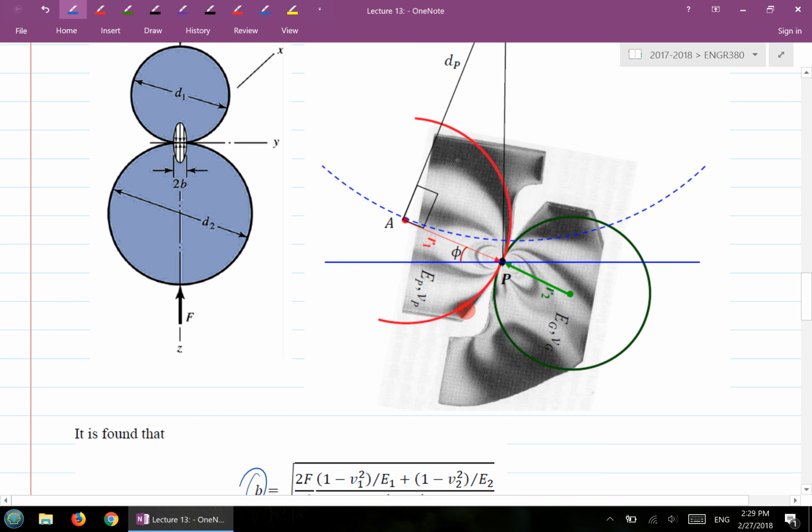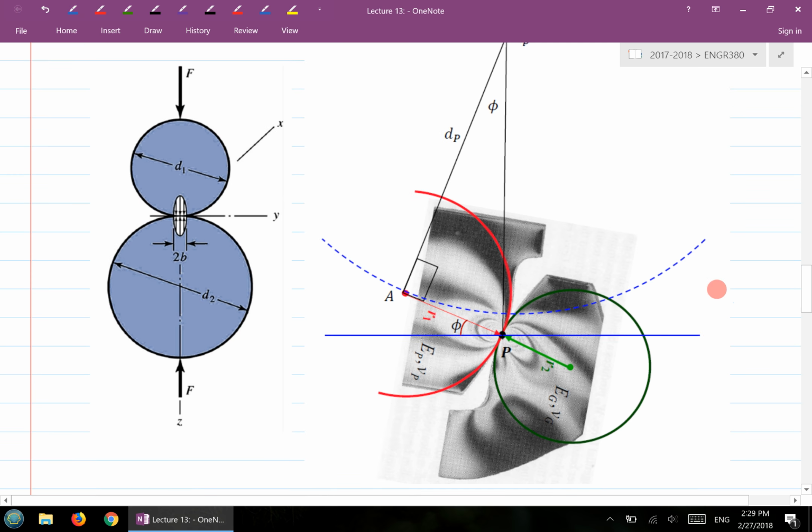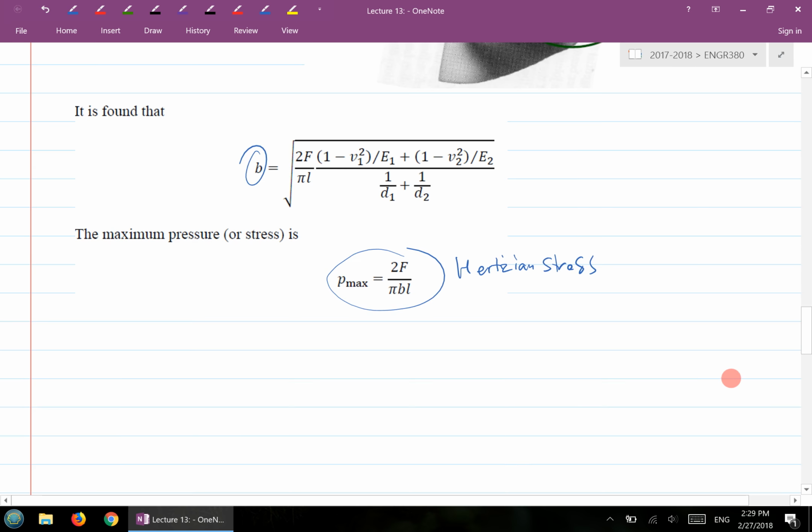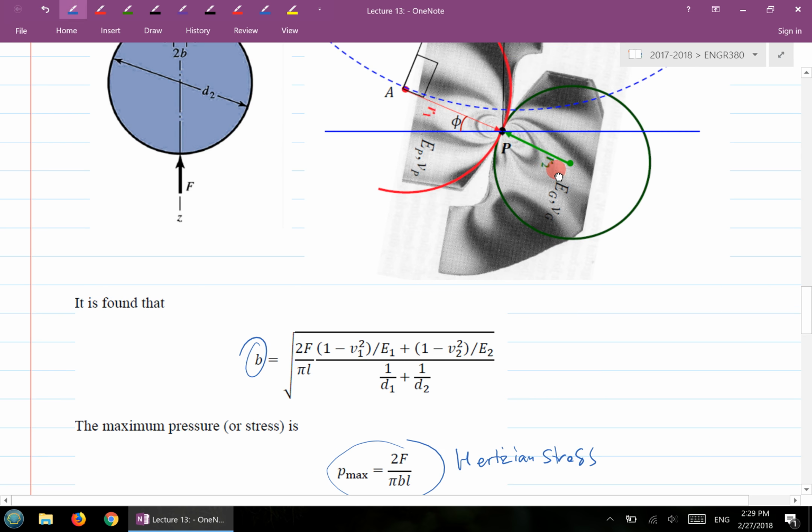And the length of the cylinder is basically the face width of the gear tooth. The cylinders will have radii, R1 and R2, based on the pitch diameter radius, so you can derive R1 and R2 accordingly.